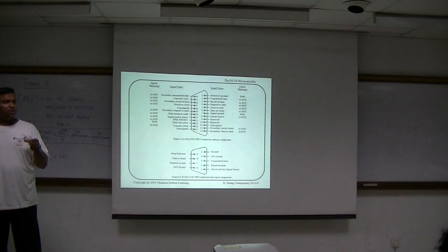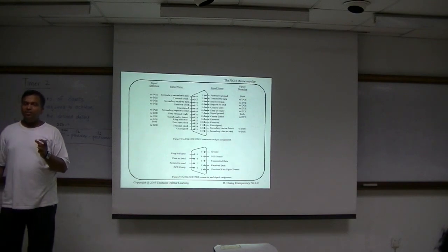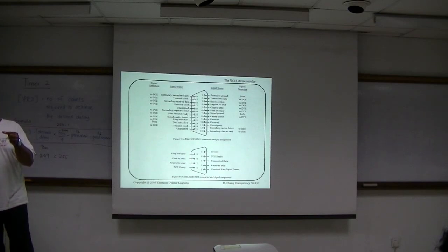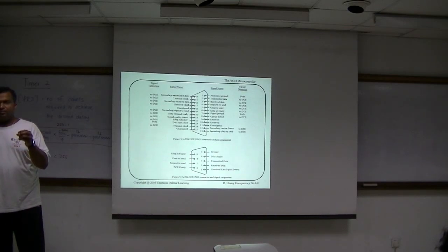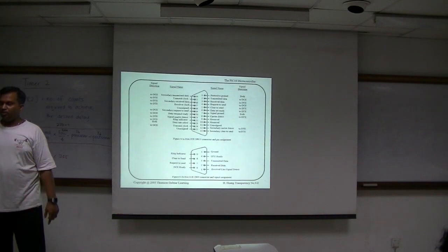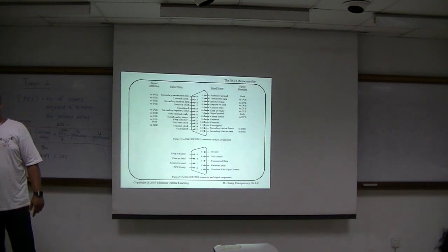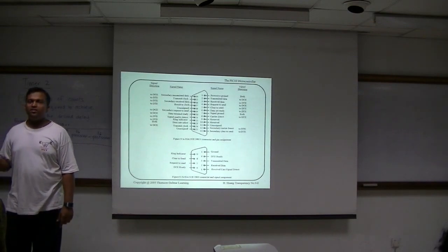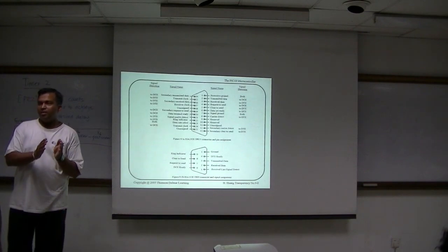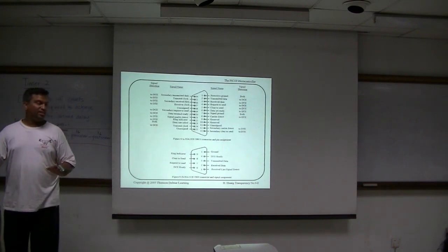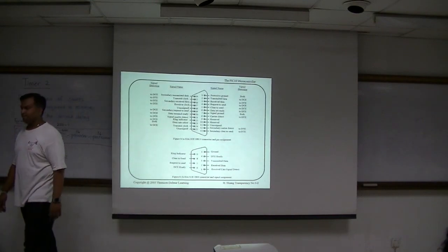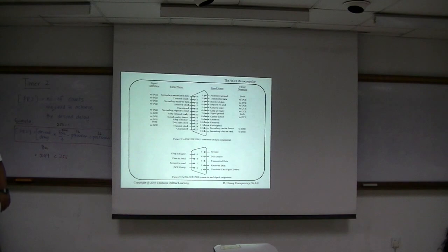Therefore, you have ICs like the Maxim 232. What that IC will do is take the data and convert it into that voltage level. When the computer receives it, it will be able to get it as 1 and 0. The translation is only required when you're communicating from a microcontroller to another device which has this port. Is it okay?